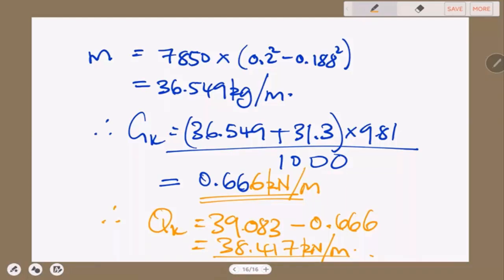That 1.6 and that 1.2, so that you see the unfactored. The assumption you can make here is that these are factored loads, although that assumption may not be valid because we did not apply a partial factor here of 1.2.